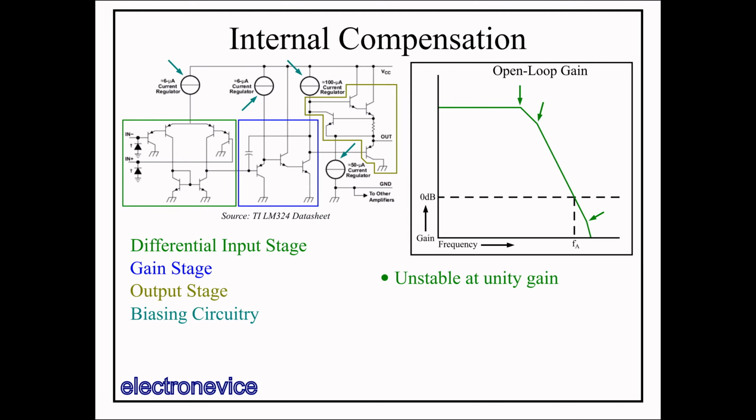However, if you set the closed-loop gain high enough, then that attenuates the loop gain by the same factor, and so you can push the transfer function into a stable region. So it could operate at high gain. In the early days, high gain and bandwidth were more important, and as we'll see in a moment, the common method of internal compensation of an op-amp will reduce the bandwidth significantly. And so if you were operating with a low closed-loop gain, you would use external compensation.